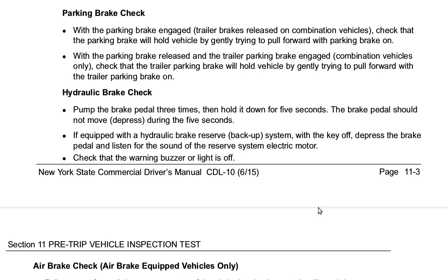Pump the brake pedal 3 times, then hold it down for 5 seconds. The brake pedal should not move, depress, during the 5 seconds. If equipped with a hydraulic brake reserve backup system, with the key off, depress the brake pedal and listen for the sound of the reserve system electric motor. Check that the warning buzzer or light is off.